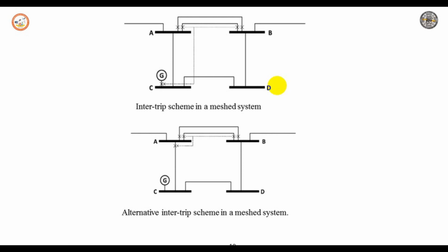So with multiple generators feeding the same bus or nearby buses during a larger power flow region, in such conditions the hosting capacity which we discussed in our previous slide could be even smaller or even sometimes zero whenever this n-1 principle has to be fulfilled. The network is reproduced in the second figure. What you are seeing is the network that is reproduced.